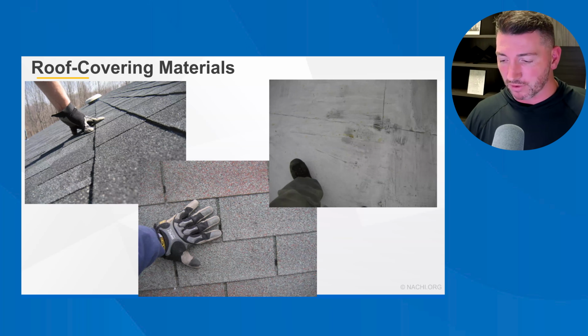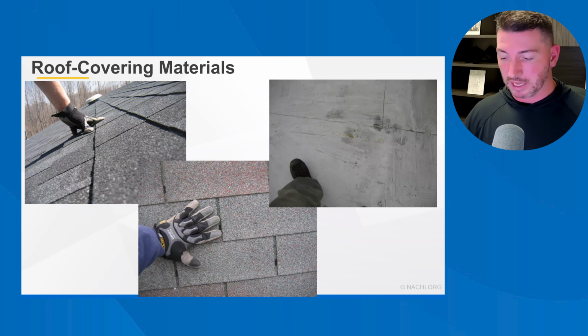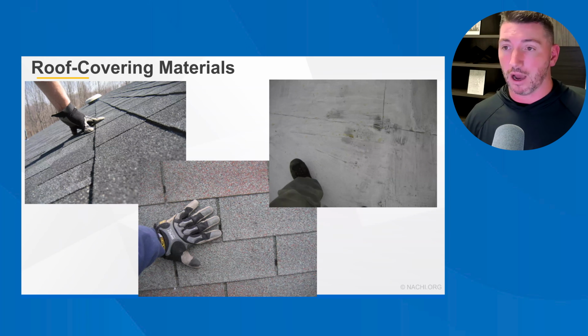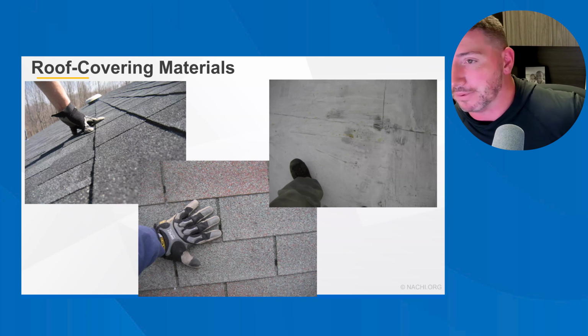For example, a built-up roof covering is a common roof covering for houses and buildings with relatively flat roofs, and it's made up of 2 or more layers of felt cemented together and surfaced with a cap sheet, mineral aggregate, smooth coating, or similar surfacing material. As a home inspector, you'll only be able to observe the top exposed roof layer. And if you've never seen how they do built-up roofs, they hot mop asphalt in a lot of instances over layers of felt paper.